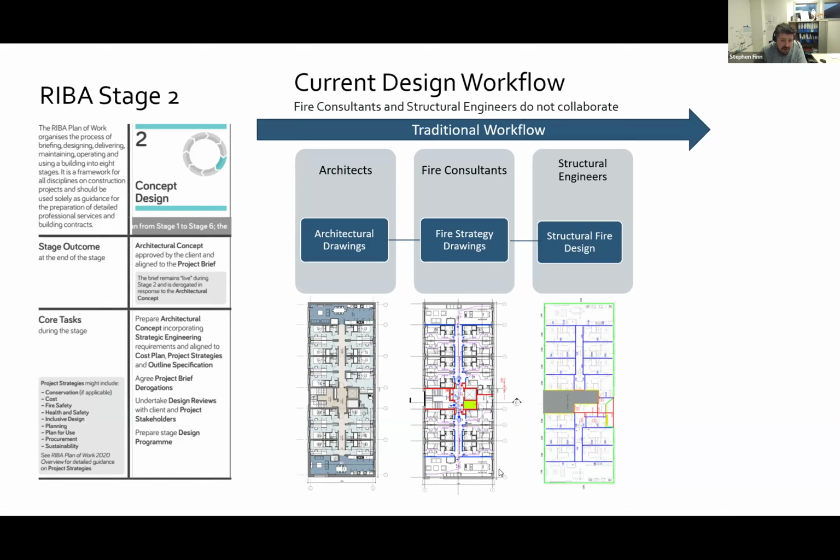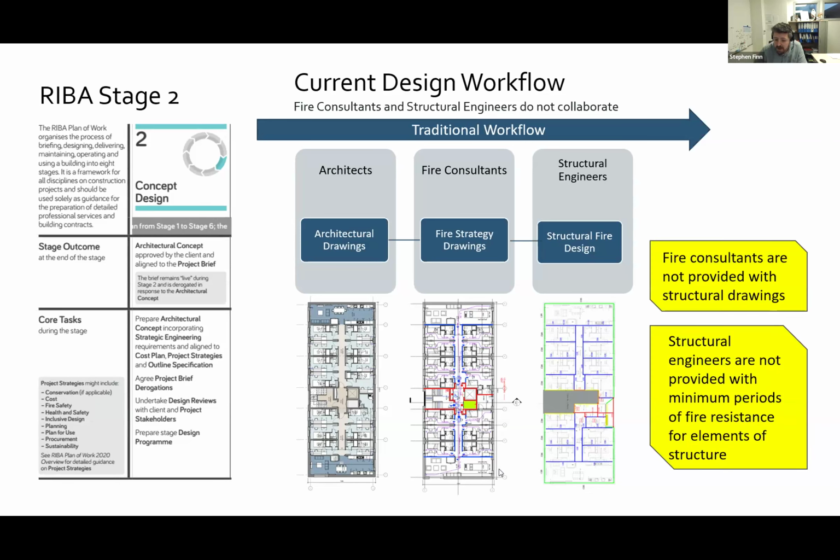Typically then what we get is a fire strategy drawing that is again based off a traditional design method and not an MMC design solution. The issue with this is there's no real coordination between fire consultants and the MMC structural engineers or the system owners, and there's no real collaboration between the tested system and the fire strategy at early stages, which can cause a lot of back and forth and a lot of confusion as to what the fire strategy actually should be.